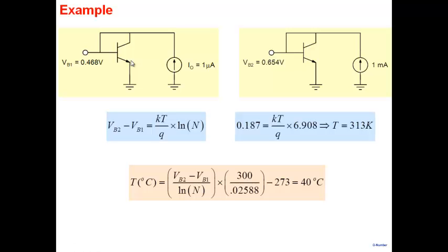But I can arrange the currents such that the power dissipation in my transistors are very low. So both the transistors are at reasonable temperature. That's a very valid point that this one transistor could be at a different temperature than this. But I can arrange the currents such that the power dissipations are not high and the currents are almost the same. The temperatures are almost the same.